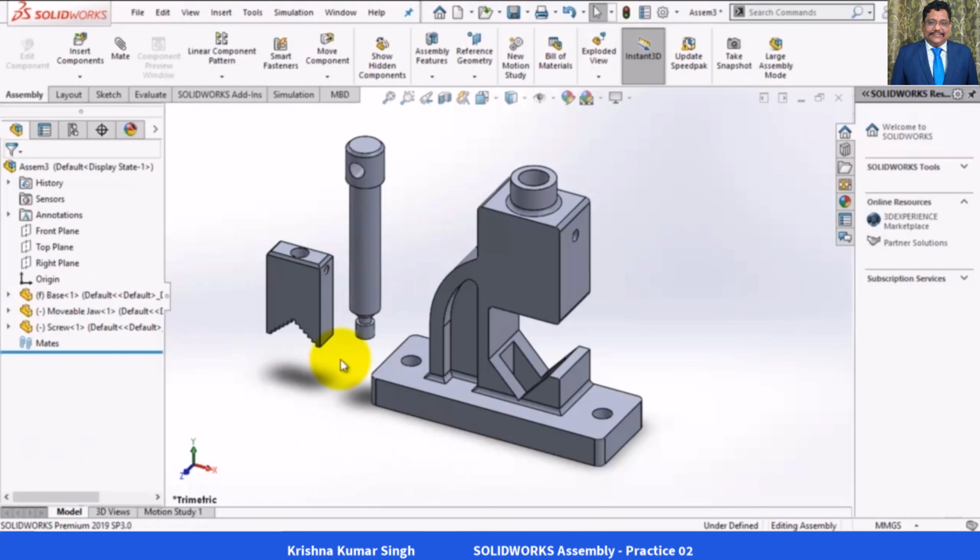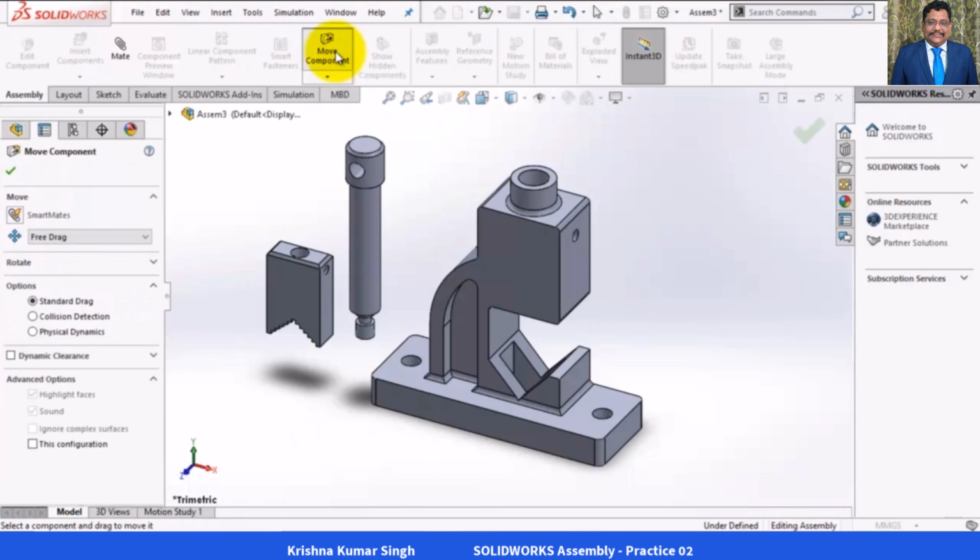Now first, we need to assemble the screw and the movable jaw. For that, we need to fix the movable jaw first. So select it, right click on it and then choose the Fix option. Now invoke the Move Component Property Manager by clicking on this Move Component tool here. Choose the Smart Mates button.